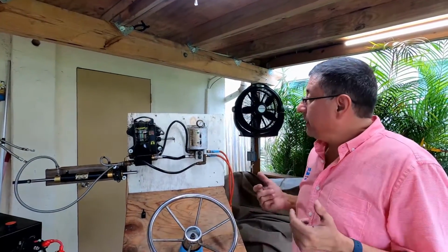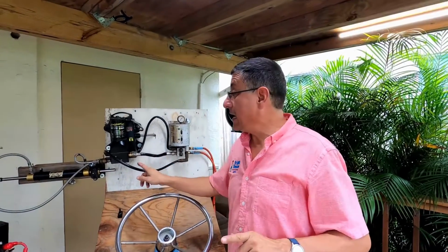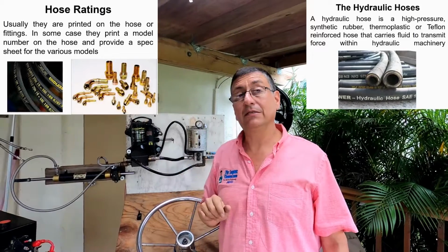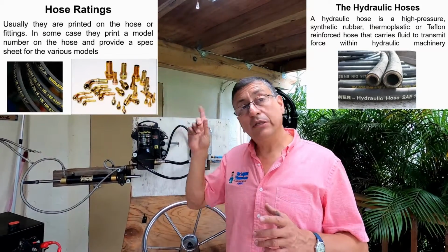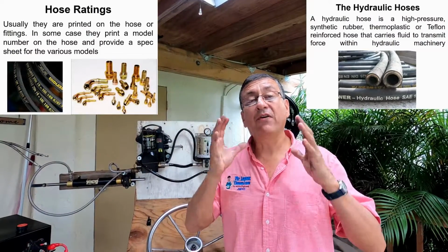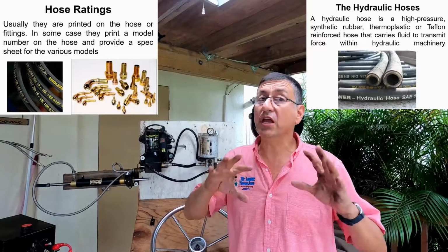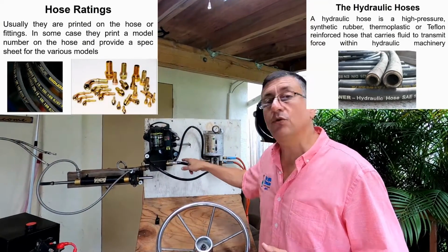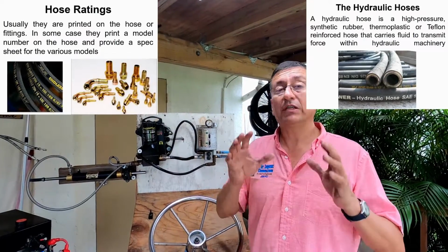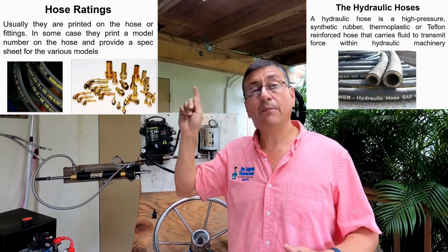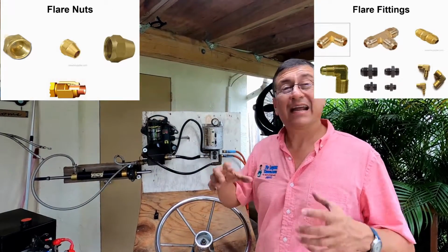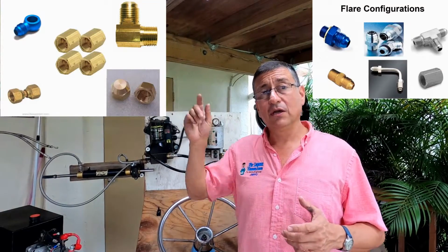All right, this is the typical hydraulic system. Important: the lines, the quality of the lines, the quality of the fittings. Those lines are special lines. Those lines are reinforced lines. Those lines are hydraulically approved. Never try to use generic lines because you know the pressure that you administer in those lines. It's a heavy pressure. For that reason, use only marine approved hydraulic lines. And of course the fittings, special fittings. There are a lot of fittings in different dimensions.